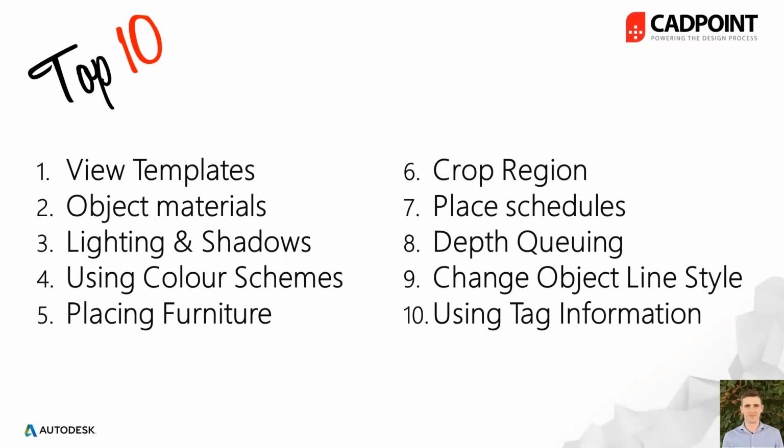What we're going to cover today are top 10 tips contained in this demonstration style presentation, and we're going to range from things such as view templates, object materials, lighting and shadows, color schemes, placing different objects, using your crop regions, placing schedules, depth queuing, change your object line styles, and using tag information in your drawings as well. At the end then we'll leave a couple of minutes for questions, and happy to answer anything that I can today.